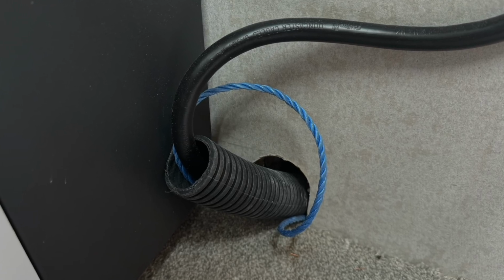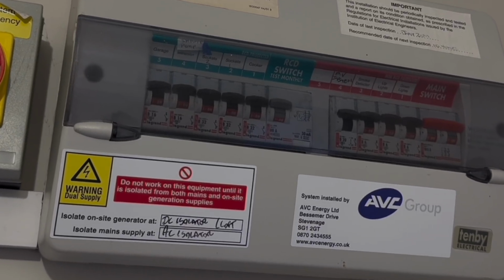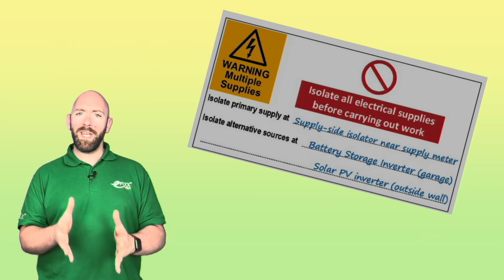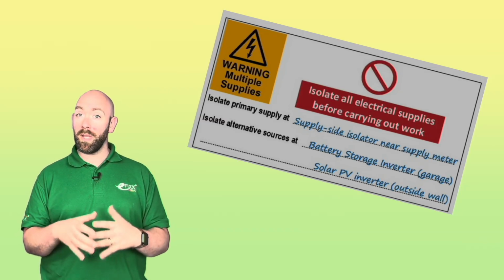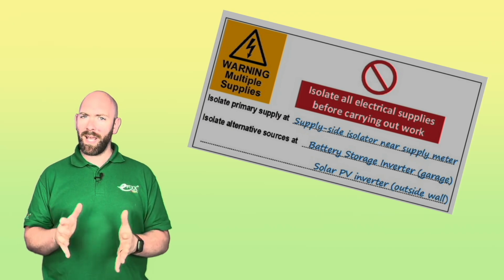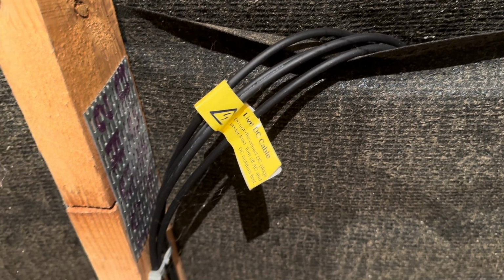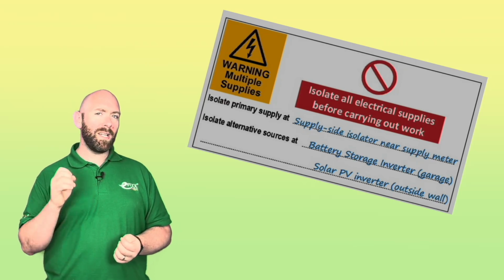So now we've considered how the cables are going to be installed, we now need to include our notices and warnings. With any PV installation, we have to make sure that labels are clearly visible for homeowners and future electricians who may work on the installation. So on or near the incoming supply or consumer unit, a multiple supplies warning notice with details where the isolators are located, and where they are located is mandated as well in the code of practice, which says DC cables should be labelled PV array live during daylight or equivalent, with labelling required every 50 to 100 metres considered sufficient. But different installations with more complex cable runs may need additional labels.